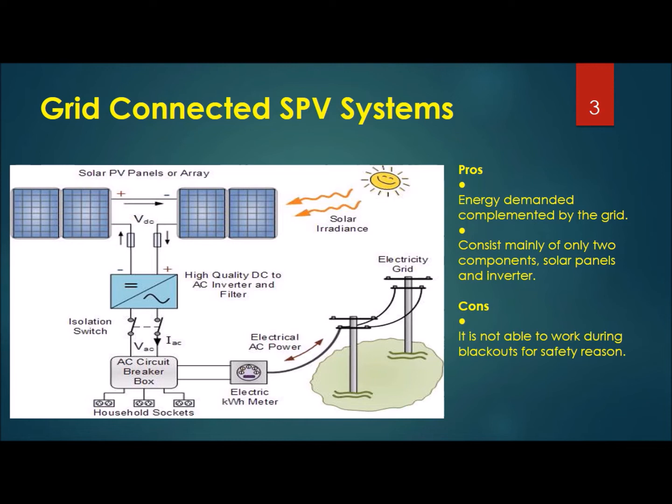This enables the photovoltaic system to supply power to the local loads or feed to the supply when photovoltaic power is greater than load demand power, and at night or during high load demands, when the power required by the load is greater than the photovoltaic generated power, the excess power required by the load is received from the grid utility.